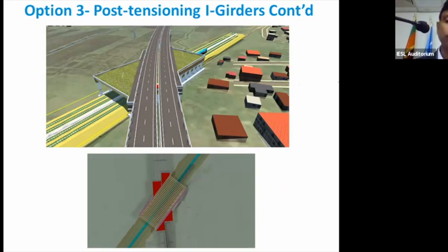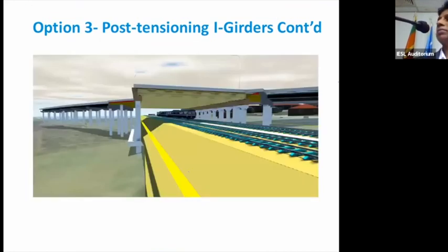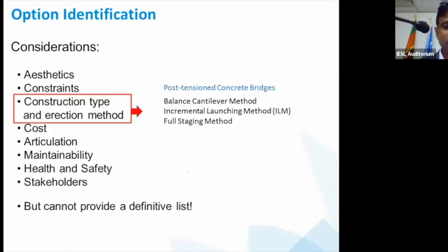The picture below shows how we stack the girders. Girders are not towards the direction of the traffic, but kept perpendicular. Mainly, we want to satisfy the clearance requirement, as you see in this picture. That's considered to be an option, but it is technically feasible. Aesthetically, you can argue a few things, and commercially also, I don't want to quote on these things, but you need to think about them.